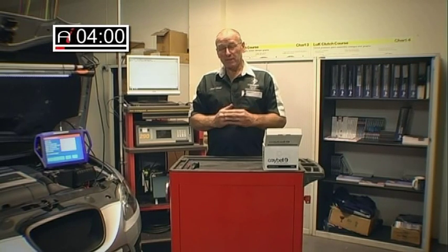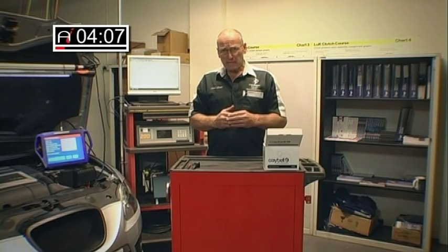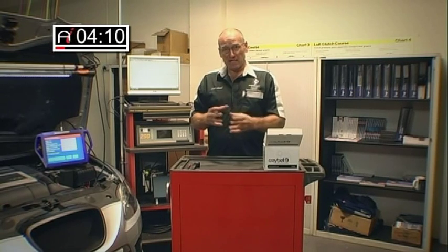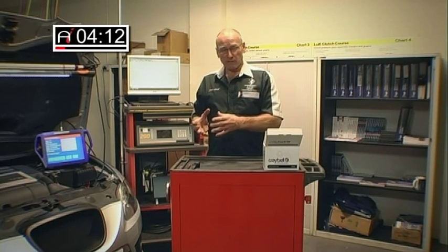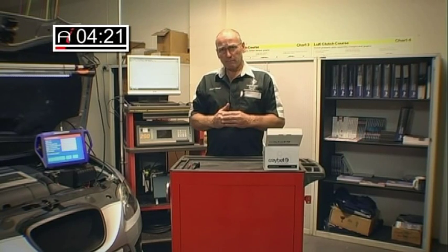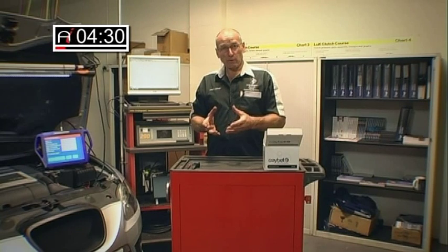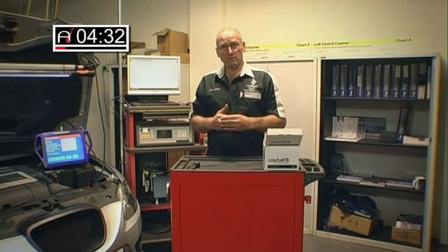So in effect what will happen is the air mass meter will measure a value of air mass. The calculation will be made to add the correct amount of fuel against that calculation and others, of course. The air is then pressurised with a turbo and then potentially lost through an induction leak. So in effect what can happen is you end up with an engine that's overfueling. So you may end up with the rather ridiculous situation of an air mass meter value which is correct, but an engine load value or lambda value which is showing lean of normal.